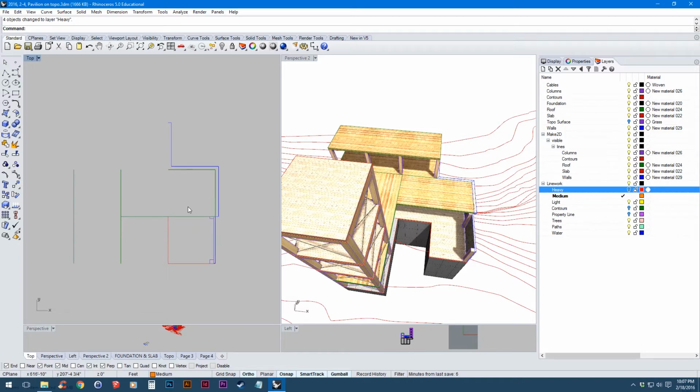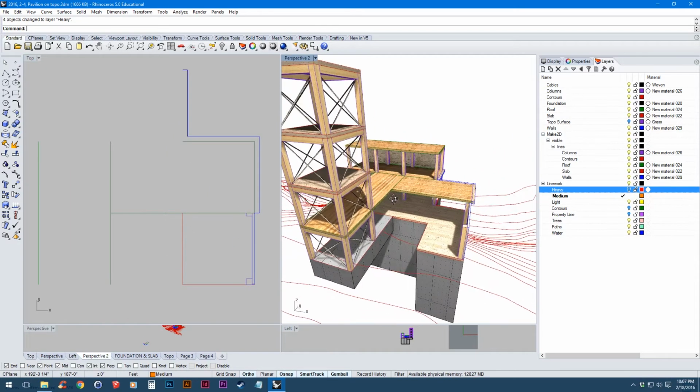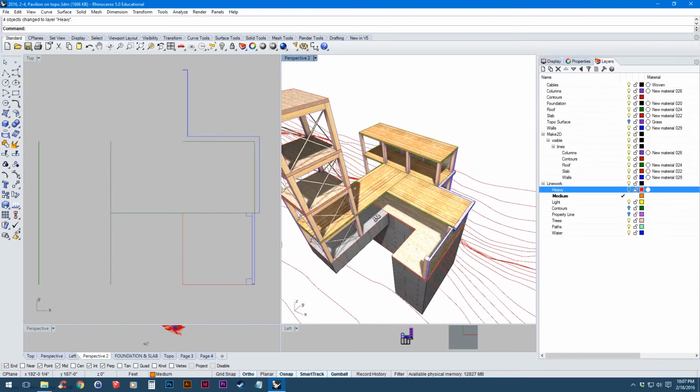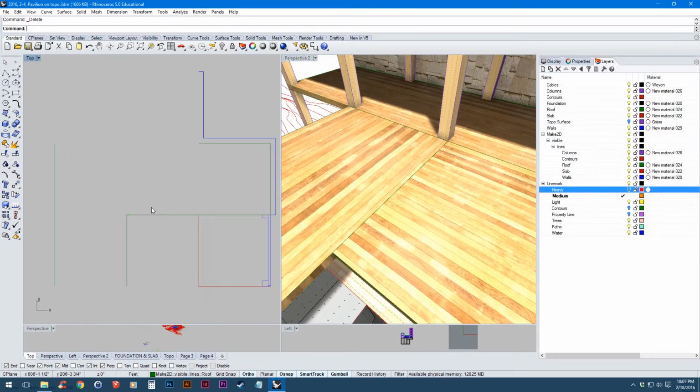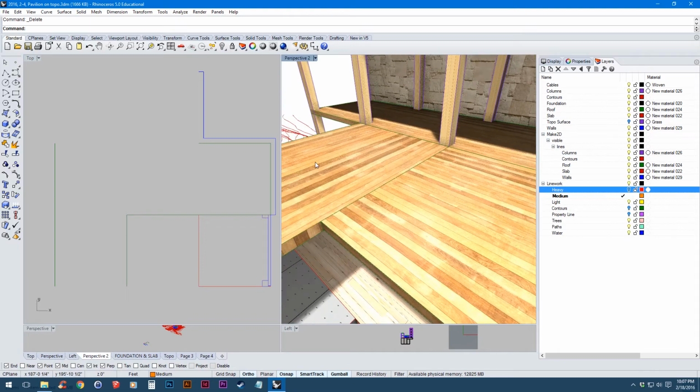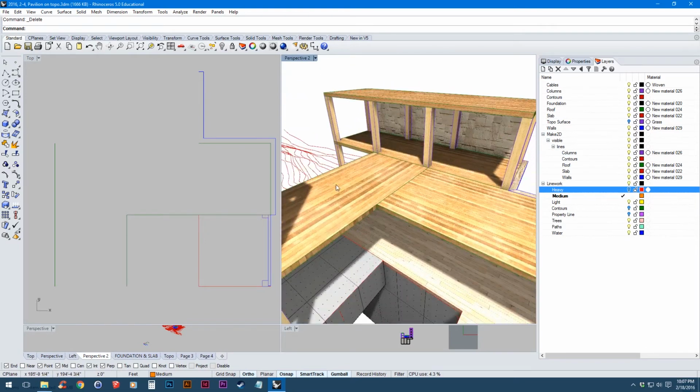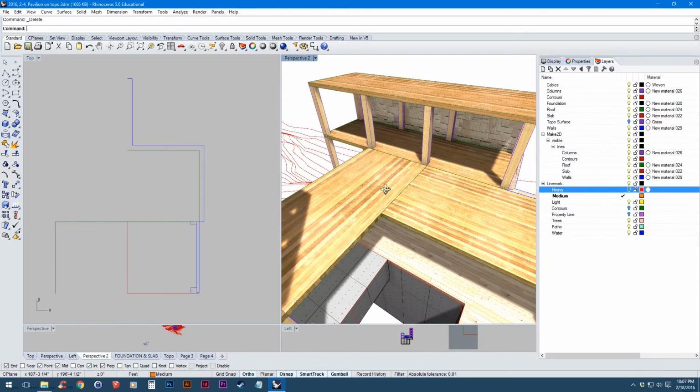All right, the next thing I'm going to do is move the light lines into that layer. So in this, it would be whatever object is at the bottom of the model. So that would be these two lines right here. Then also any line that's delineating a change in material or on a surface. So actually this line right here, which is showing right here, there actually most likely would not be a line there because they're still the same material. I just modeled them as two separate planes. So I'm going to leave that the way it is.